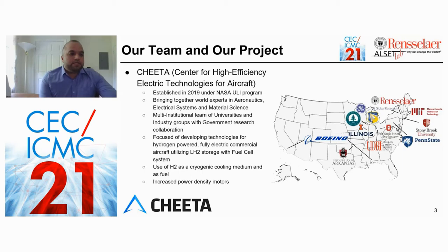The aircraft uses liquid hydrogen storage with a fuel cell system to power the superconducting motor. Liquid hydrogen is used both as a fuel and as a cryogenic coolant medium here. One of the reasons for using a superconducting motor is the increased power density, which is important in a weight-sensitive application such as an aircraft. This presentation is focused on the cooling system, which uses liquid hydrogen to cool the superconducting motor.